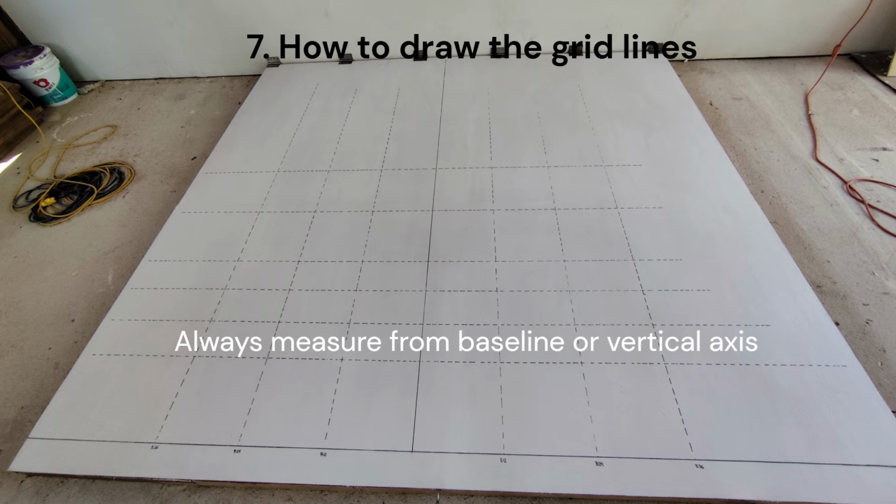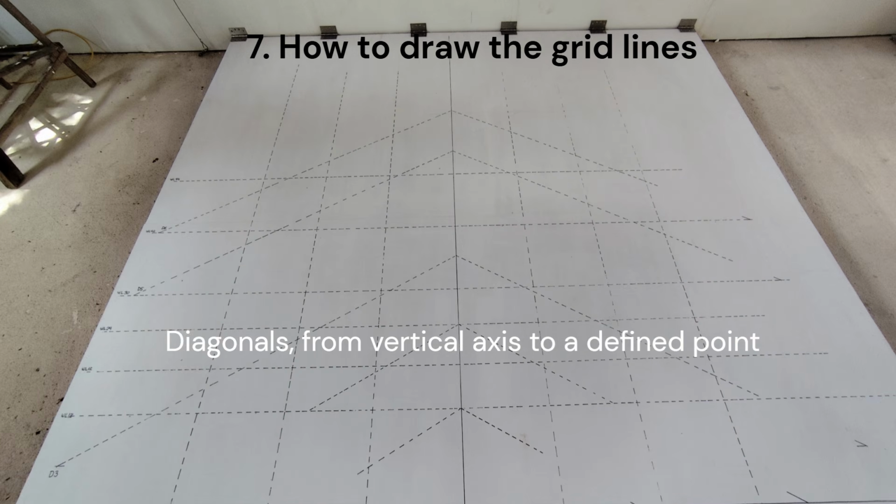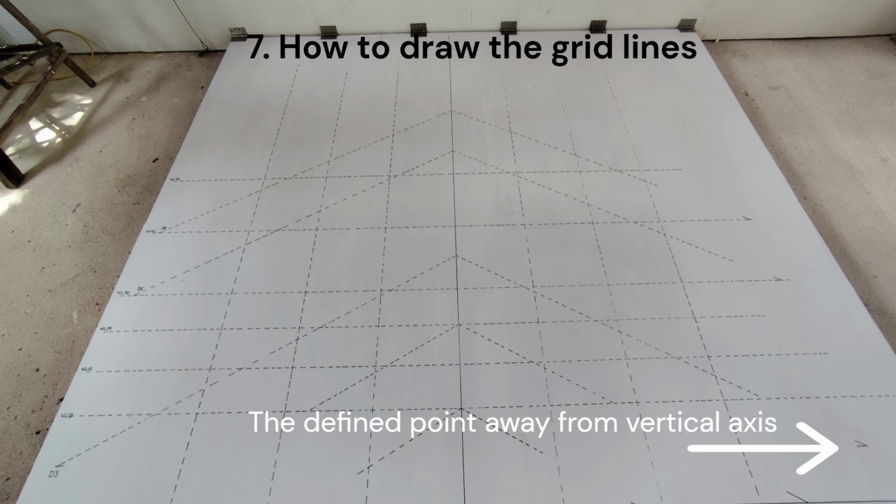Never measure between the water lines. Now draw these water lines dotted with the same pen color as the baseline and the vertical line. Do similar for the buttock lines. The diagonals are slightly more tricky to draw. It's assumed you have determined how they are defined, with 1 point on the vertical axis and 1 point as the drawing states. Draw these dotted as well with the same pen color. You will end up as the picture shows.